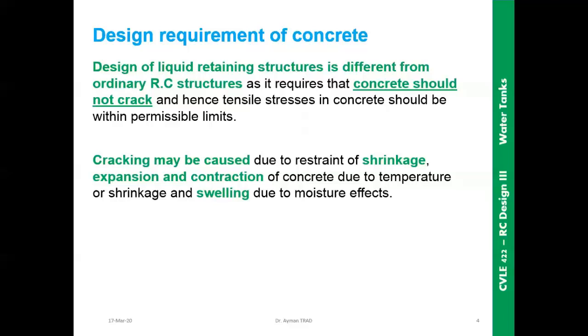Then this difference of temperature will generate contraction or expansion of the walls or of the structure in general. So this movement will create internal forces in the section. These internal forces will pull the concrete apart, creating tensile forces and cracks. Of course we know that concrete is weak in tension, so these internal tension forces expose the concrete to tension and, being weak in tension, cracks will occur.